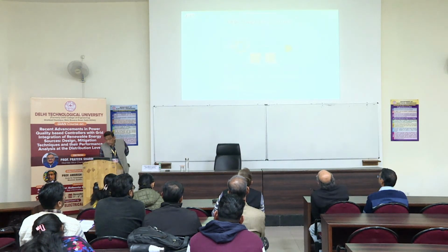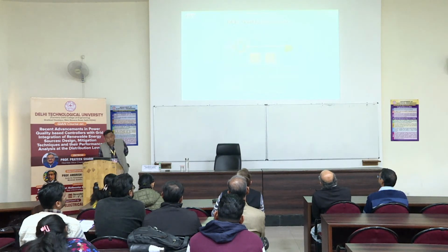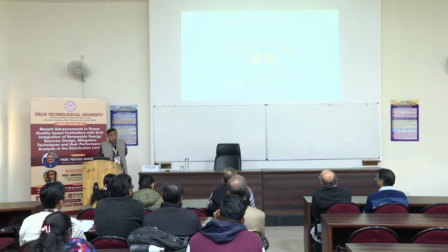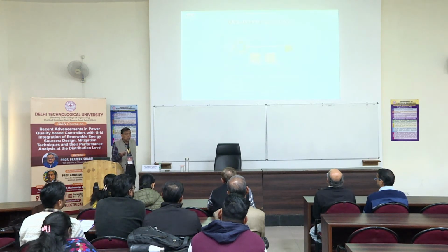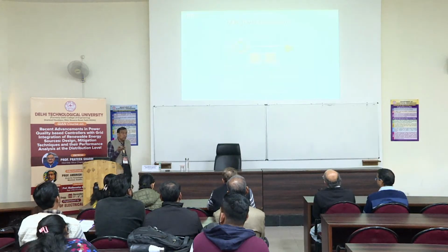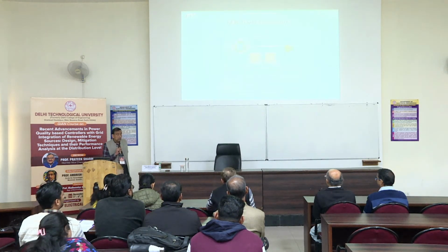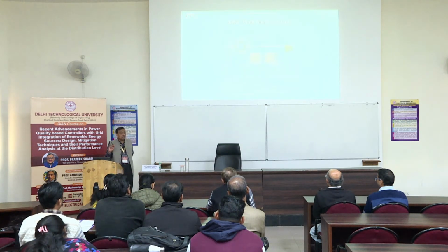Here, the stator winding is directly connected to the grid, while in PMSG you have a back-to-back full-size converter. So when the stator is directly connected, this is the problem. We will discuss this. What is the problem, because the stator has inductance?